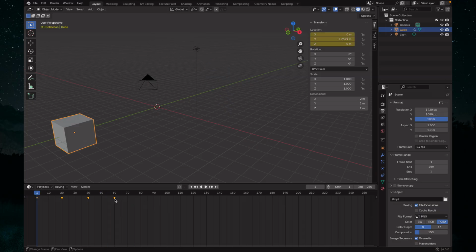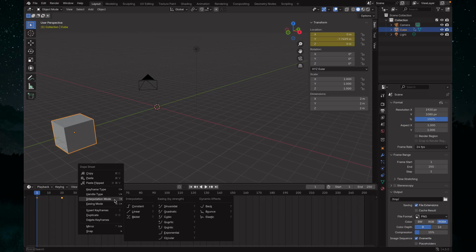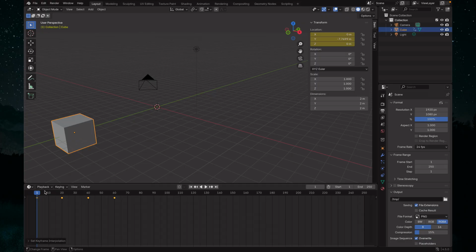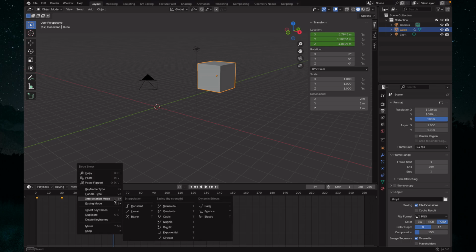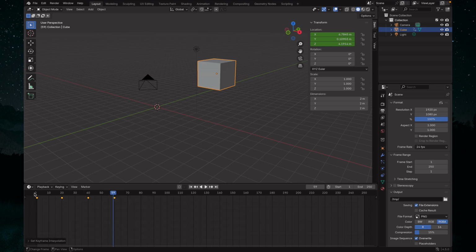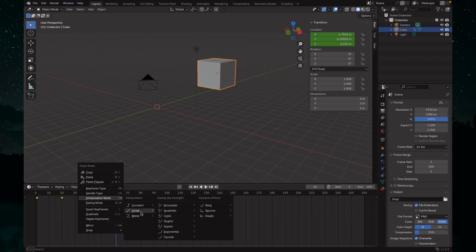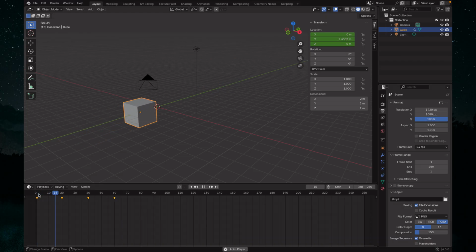Then there's also what we call, let's right click, interpolation mode, linear. Now this linear is constant. Even if it's in a corner, it wants you to stay at a constant speed. As you can see, it's moving at a constant speed. It's not like the first one. The first one was a bit slow every time it reaches a point. Let's go back. You can see that it reaches the point and first slows down. But linear interpolation mode is moving very, very constant.